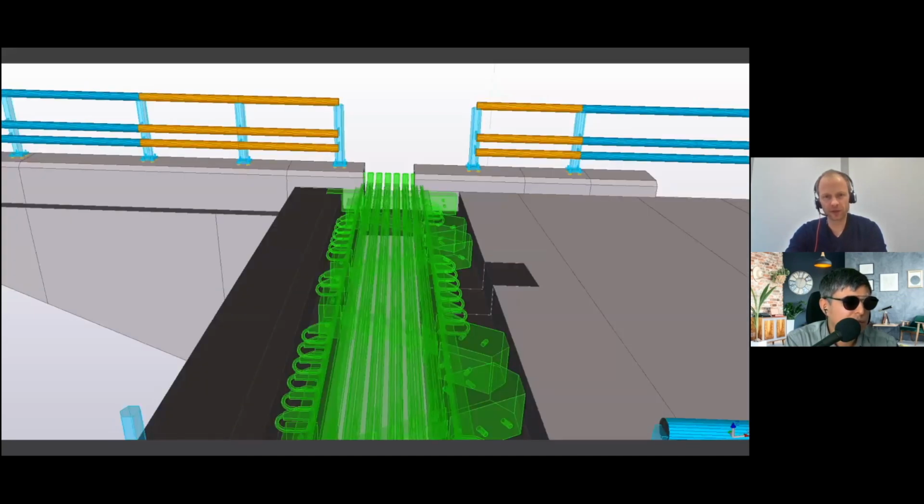So having a look at the same joint, just in different ways of displaying it, we can now very clearly see what we need to adjust to make this fit the structure. The difficult thing here is that when we start the project, we have no idea who the deliverer is. So we need to reserve some space, but we do not want to reserve too much space, because then we cannot finish any of the pouring stages next to the joint.